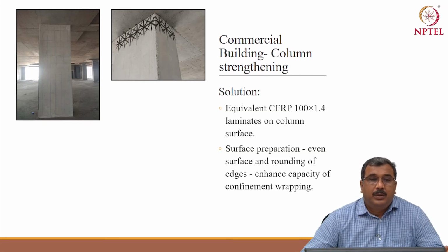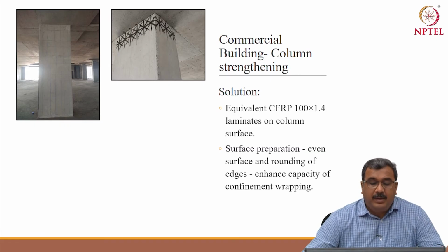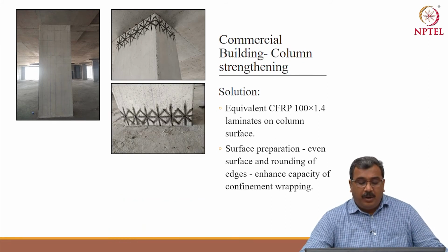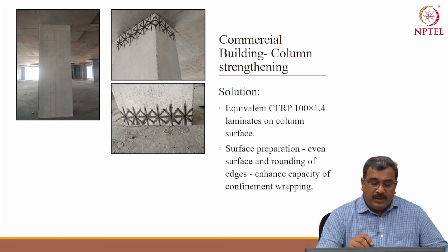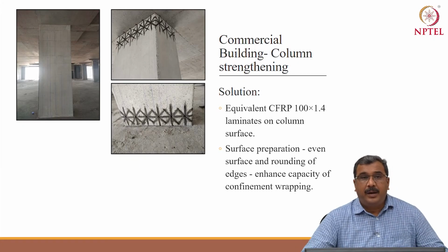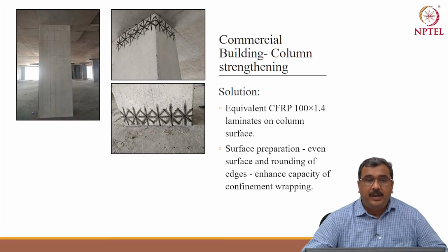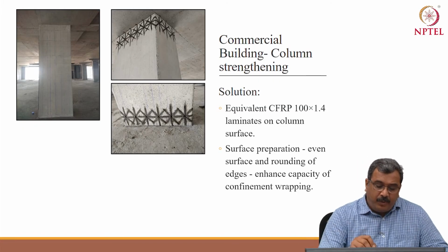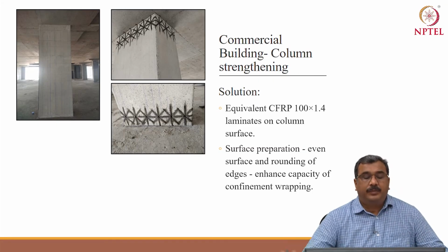Now, to avoid delamination, fiber anchors made from carbon fiber were installed at the top and the bottom of the column. You can see a hole which has been drilled, 10 mm diameter and 100 mm depth. The stem of the anchor is inserted inside and grouted using epoxy, and the fan portion is inserted in the slots.